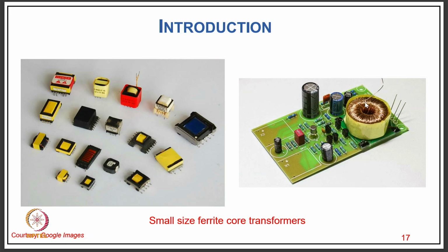New applications also emerge, like welding and other uses, even for many electronics equipment, as well as typically in power electronics applications for the purpose of isolation for gate drive and other applications. There we use this high frequency transformer for many purposes. One is isolation; another is to get many output voltages so that we can convert into many